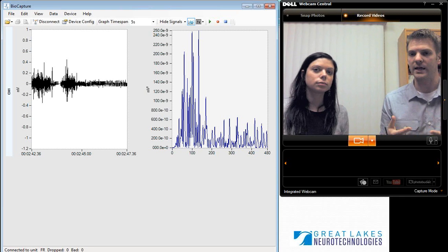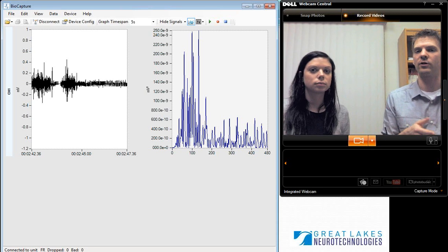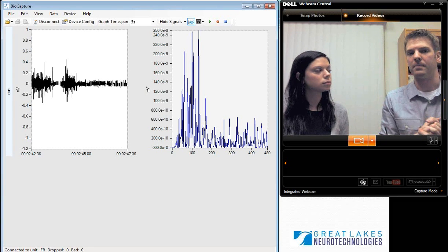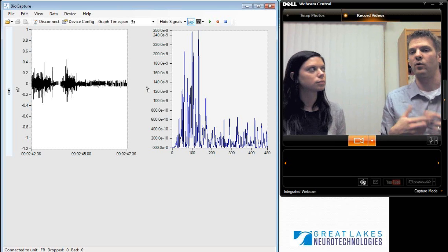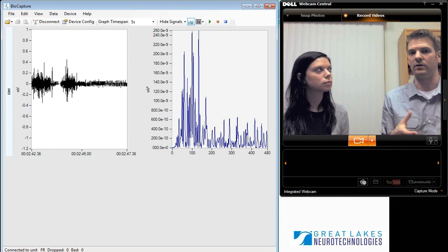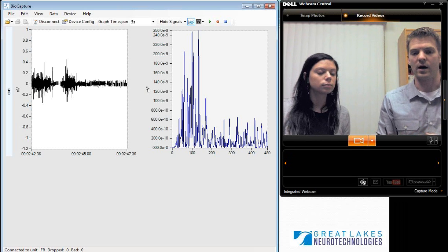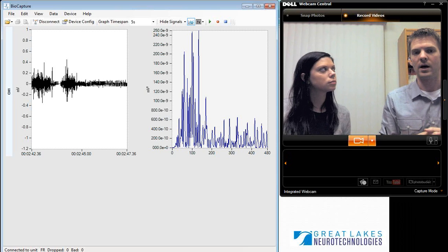Now, in many cases, the EMG signal is not something where you're trying to accurately measure every peak and trough in order to compare to something else. In that case, a grosser digitization of that signal is more than acceptable, especially if you're rectifying and integrating the signal, which is commonly done with a lot of EMG data collection.